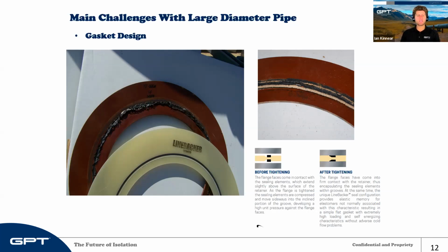So you want to make sure that seal has somewhere to compress into within the groove itself. It's called a volume void ratio. So when that seal gets compressed, it has somewhere to flow into. In this case, there was nowhere for that seal to flow into, so it flows along the edge and creates a leak. In smaller sizes, I would still think a design like this is going to have a leak, but in larger sizes, there's just no way you're going to get the compression all the way around that you need.